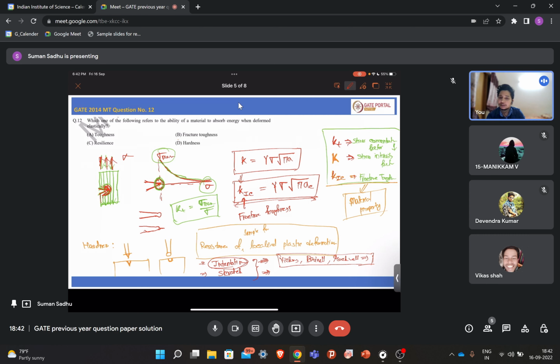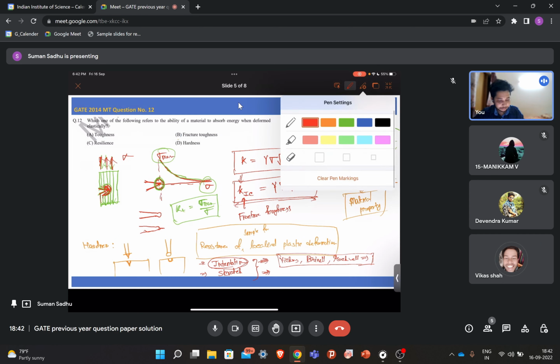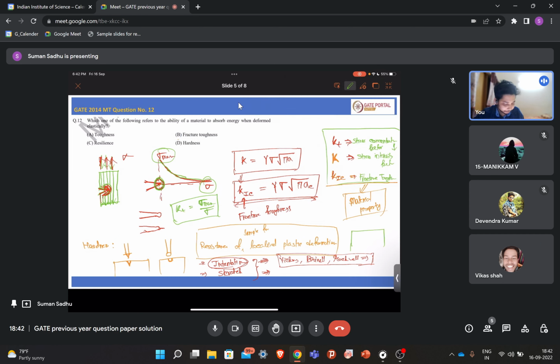No, that is like now we are going into some different thing. Let's say you have a sample, and there are two types of hardness. In case of Vickers also, when the size of the indentation is large, let's say in your sample there are various grains, right? Yes, sir. It might be a single phase or two phase. If it is a single phase region, then you can say the overall hardness of the sample will be almost the same. But if it is a two phase region, let's say these red ones are different phases.